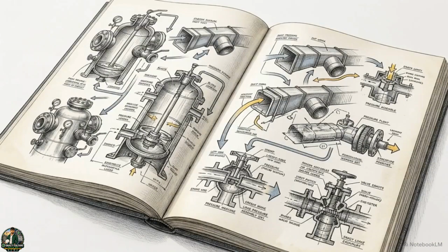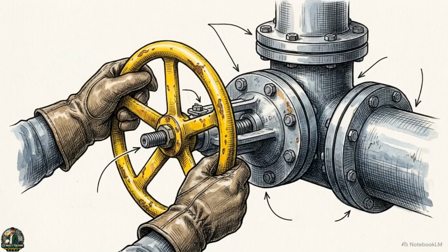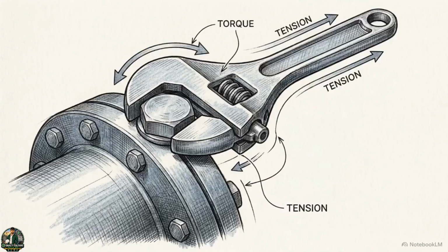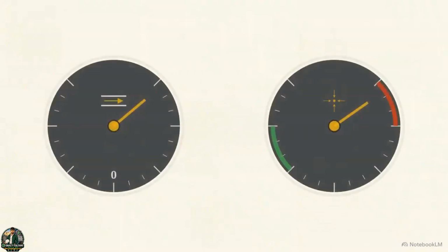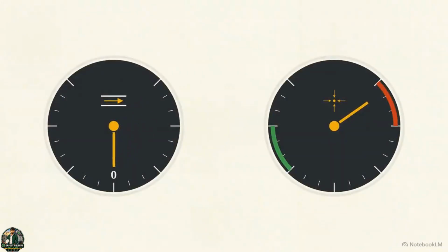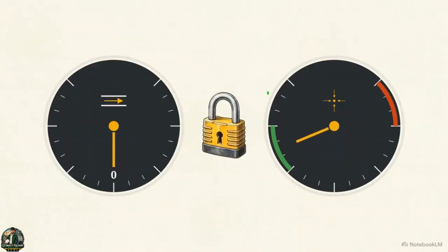Subsection 3 shifts the regulatory focus. It moves away from permanent structural design and imposes strict operational procedures for interacting with gases or vapors held above atmospheric pressure. Before a worker can loosen any joint or fastening on a pressurized vessel, the law requires an exact sequence of actions. The flow of gas must be isolated by a stop valve, internal pressure must be reduced to safe atmospheric levels, and the system must be secured to prevent explosive vapors re-entering while the pipe is open.